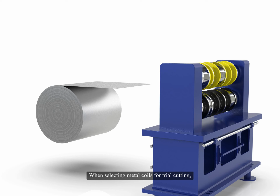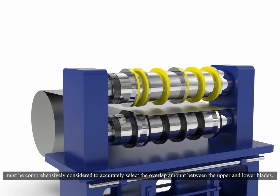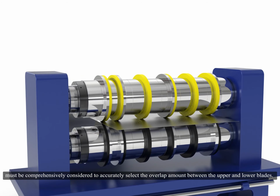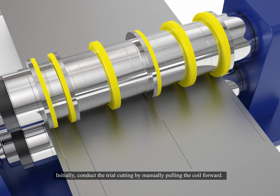When selecting metal coils for trial cutting, various characteristics of the coil, such as thickness, material, tensile strength, etc., must be comprehensively considered to accurately select the overlap amount between the upper and lower blades. Initially, conduct the trial cutting by manually pulling the coil forward.